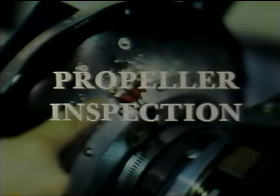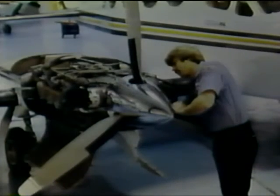Part of every inspection of an aircraft should include checking the condition and operation of the propeller system. Before you begin a propeller inspection, it is necessary to be able to interpret the manufacturer's model designation number. This number is the key to locating data that will pertain to the particular propeller installation.